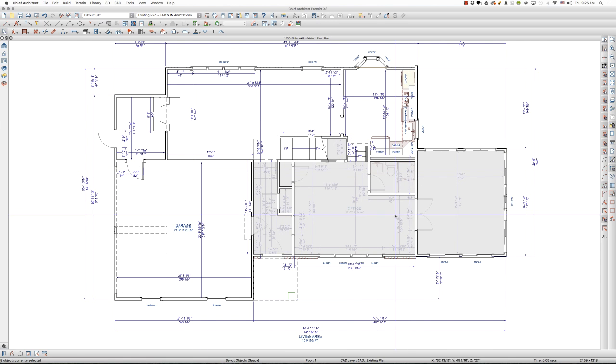Now that I've got these rooms selected, I could propagate those conditions: floor elevation 0, conditioned equals true, ceiling equals 90. I didn't select those last two, but you get the drift. If I apply properties, I could make this room floor elevation 0, the kitchen floor elevation 0, the garage floor elevation 0, but I don't want to.